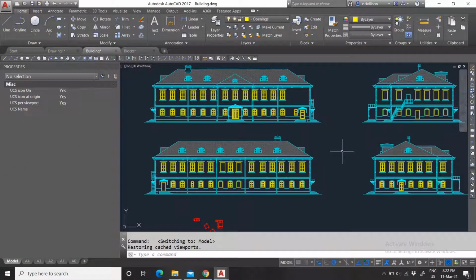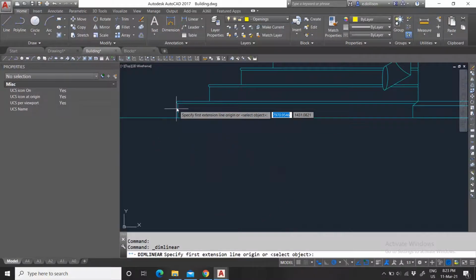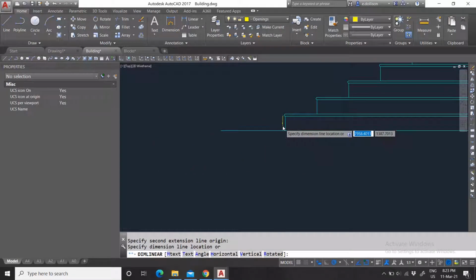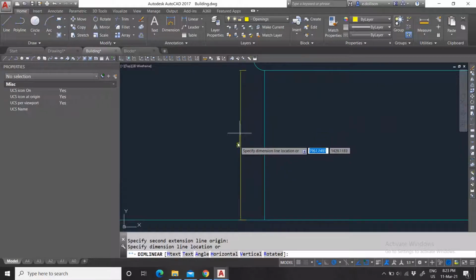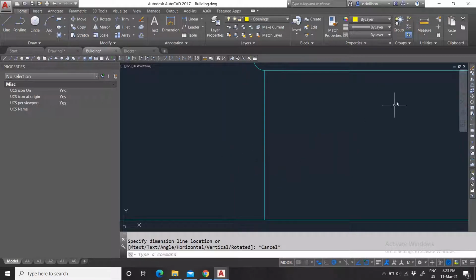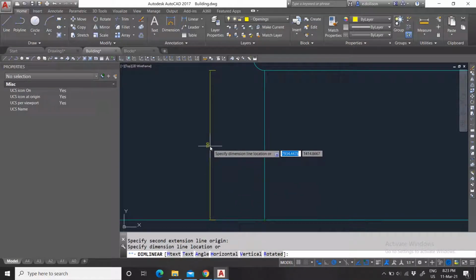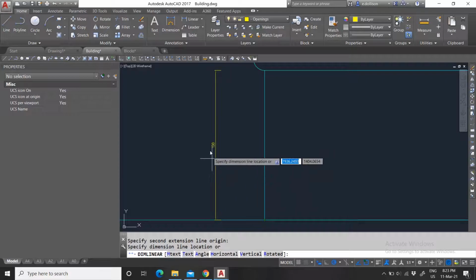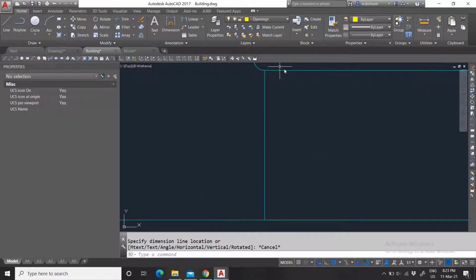Welcome back guys. Now this utility panel that is measuring, basically to measure your stuff, is very handy when instead of drawing, let's say, dimensions to measure certain stuff, like I'm going to use this dimension to measure this step, that is 130 millimeters. But instead of having to draw a dimension that basically has a lot of position already assigned to the dimension, when you want to be more precise, it's better to use your measuring tool.